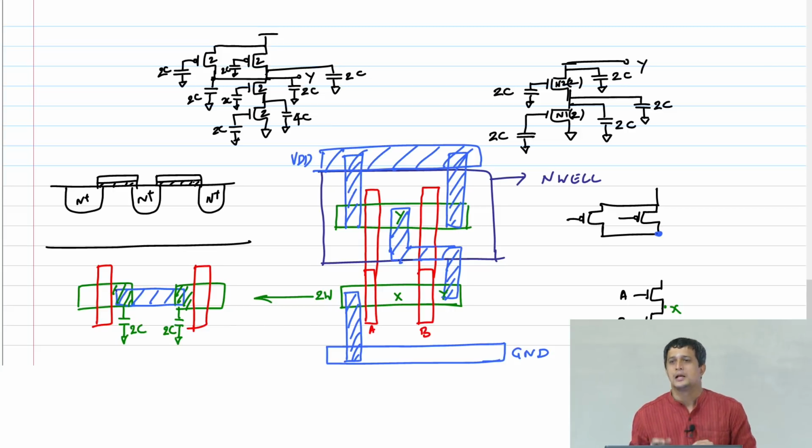For example, even in the PMOS, the diffusion is shared, right? If you look at this, the diffusion is shorted here. The difference is I need to put a metal contact here. Because I need to put a metal contact, I need spacing, and therefore I have to keep the transistors far apart. And therefore each transistor will contribute to its capacitance. So the golden rule is if it is an uncontacted shared diffusion, then you don't double count the capacitance.